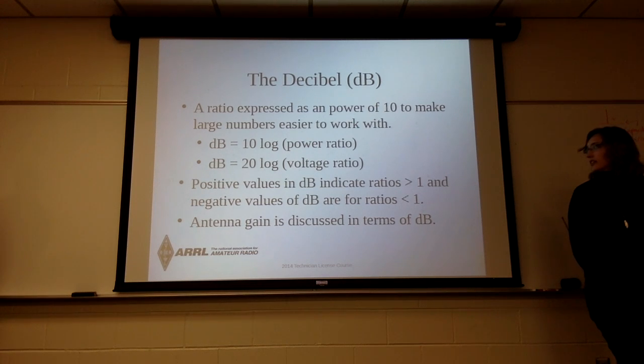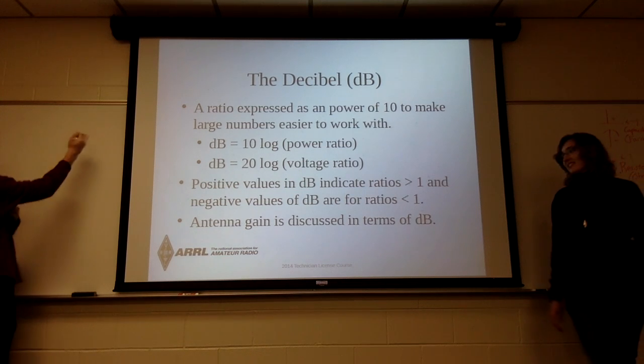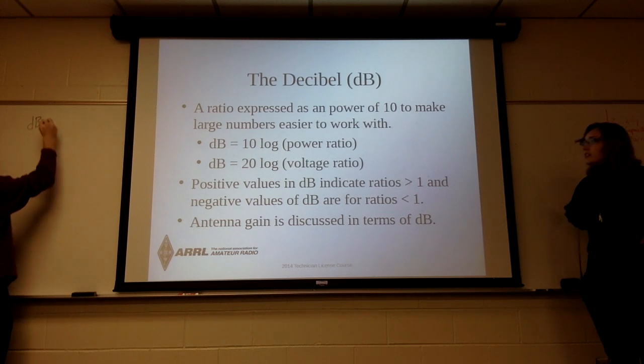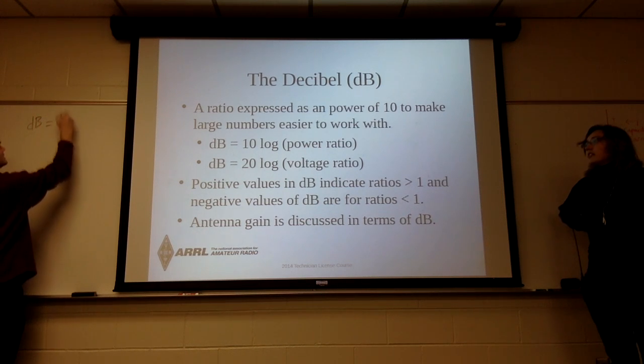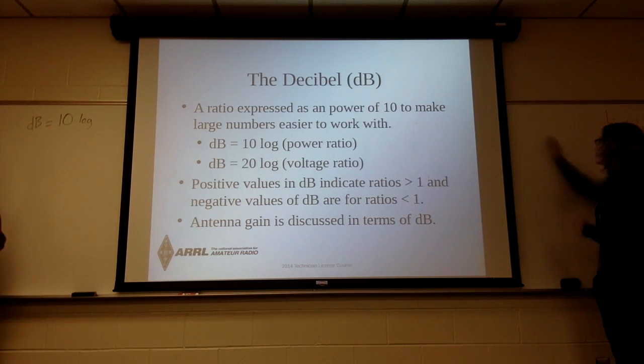Okay, back to decibels. To transfer between a regular number and a decibel, what you would do is say your decibel is equal to 10 times log, and log is logarithm base 10, not the natural log.